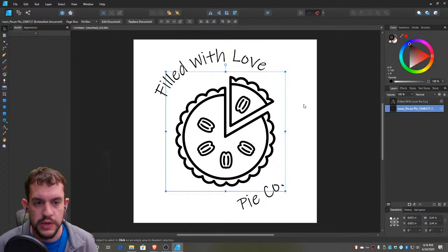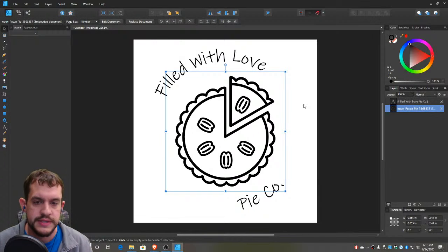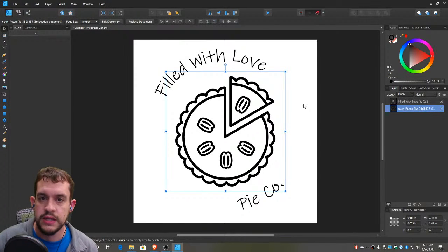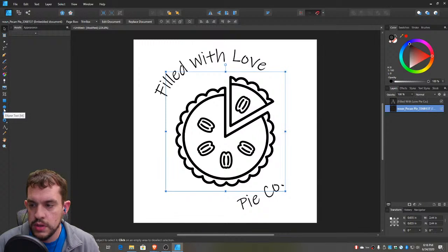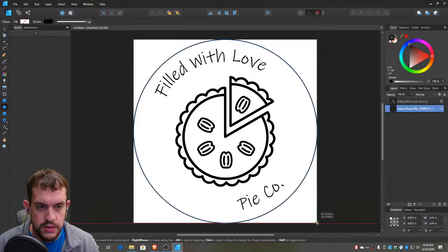And so that's working with a piece of established material, so a coaster. Say I wanted to cut this out of flat stock. In that case, we need to define a cut line. Defining a cut line is pretty simple. In this case, I still want a round coaster, so I'm going to do that.